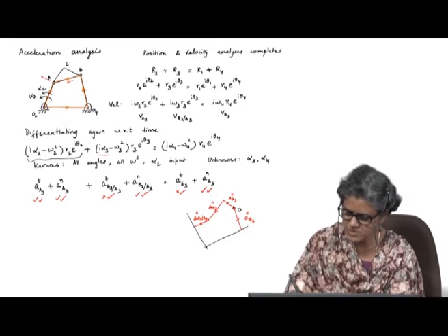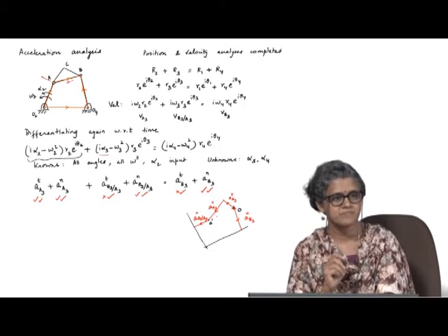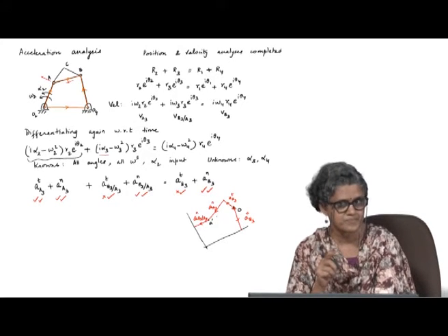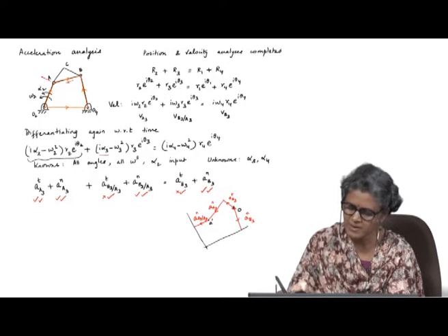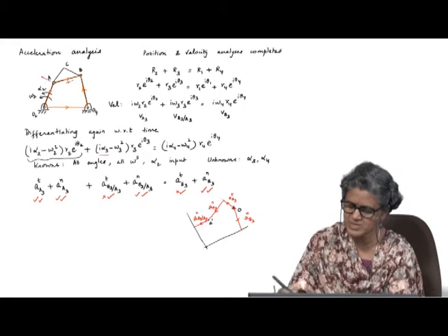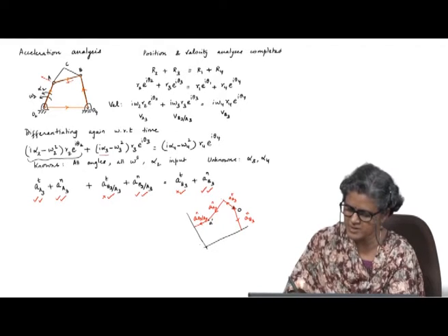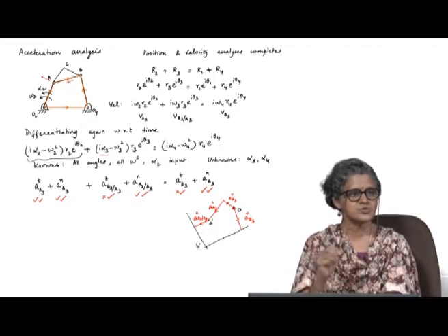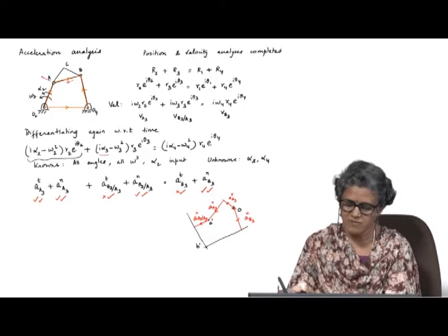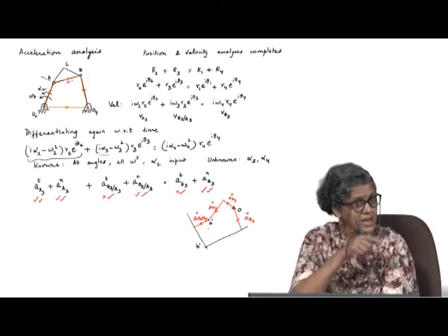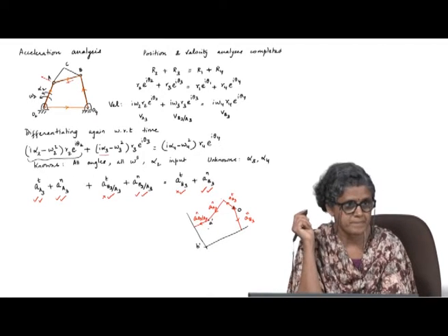Let us call it A dash, small a dash for the acceleration. Okay, this point here, the whole acceleration of A was completely known, it is this plus this. So, this point is A dash and I added the relative component there. So, this point here will be B dash, the intersection of these two will give me B dash. So, if I draw a vector from O to B dash, that will give me the absolute acceleration of point B. Okay.